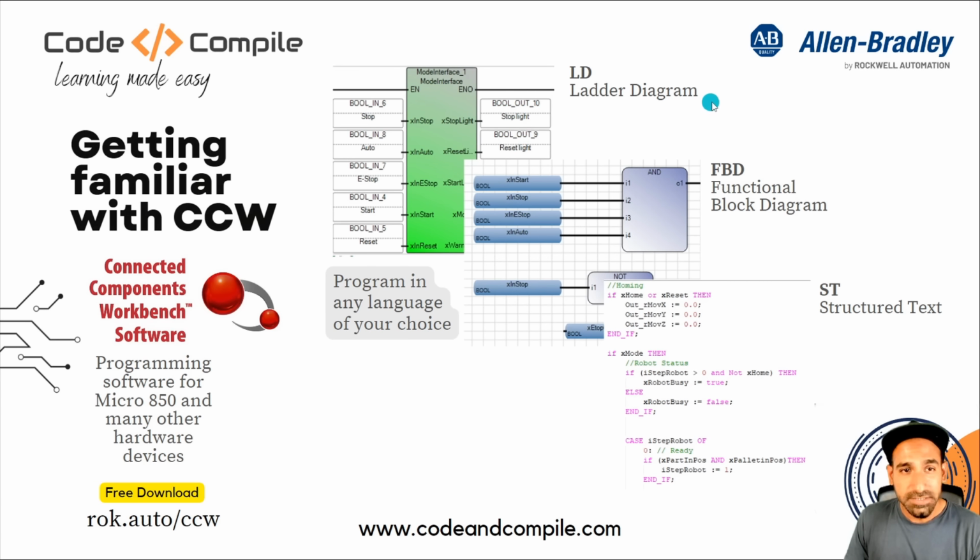And from ladder diagram and function block diagram, you can choose any of these two because both will serve the same purpose. You can use ladder diagram or you can use function block, but when you're talking about structured text, it's a bit complicated to use ladder or FBD. So you need to learn structured text to make complicated loops, and it's very easy to move values from input to outputs. We will see that in one of the lessons where I'm talking about programming a robot in this PLC. And this software you can download for free.